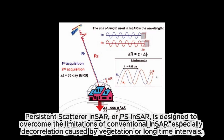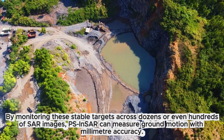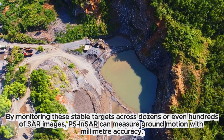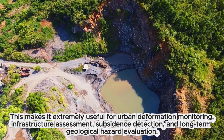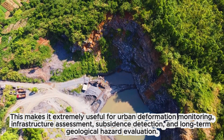Persistent Scatterer InSAR, or PS InSAR, is designed to overcome the limitations of conventional InSAR, especially decorrelation caused by vegetation or long time intervals. By monitoring these stable targets across dozens or even hundreds of SAR images, PS InSAR can measure ground motion with millimeter accuracy. This makes it extremely useful for urban deformation monitoring, infrastructure assessment, subsidence detection, and long-term geological hazard evaluation.